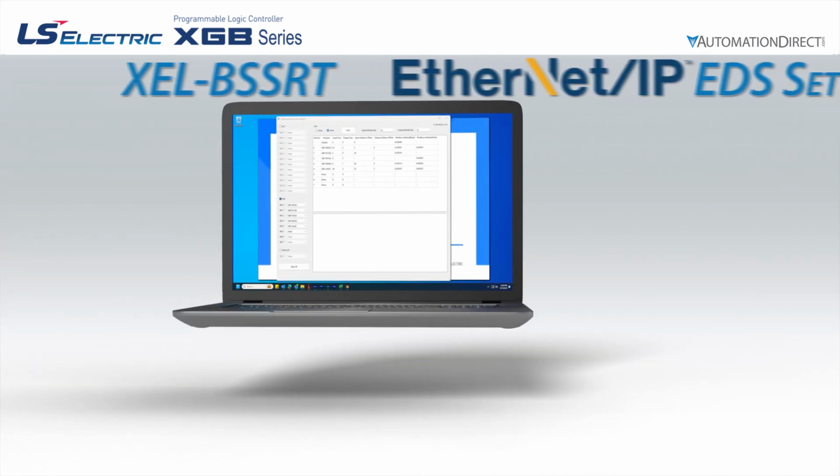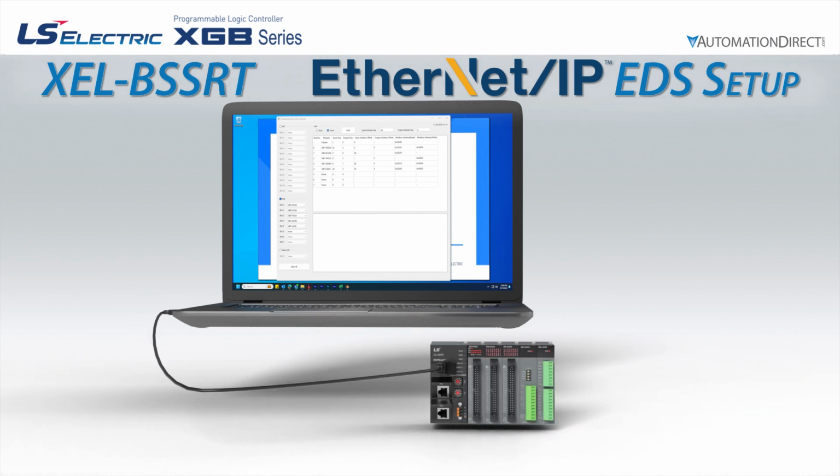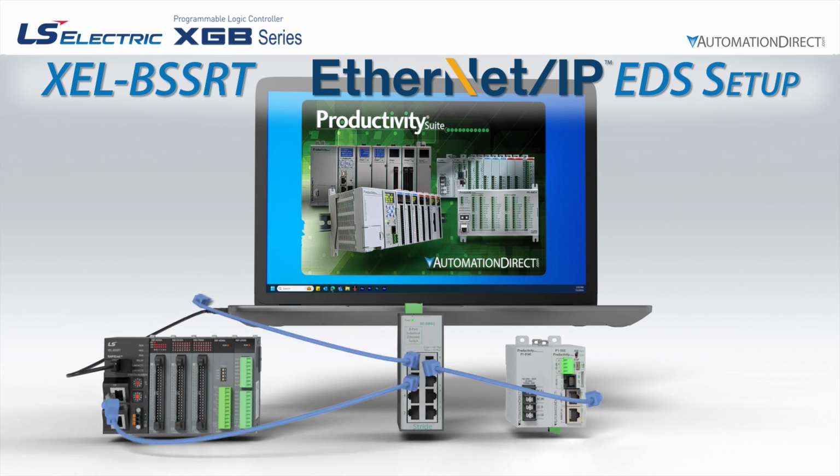Previously, we used the Addressing for Communication Devices software to establish the addressing for our BSSRT input and output information. In this video, we will generate an EDS file using the XG5000 software, and then import that EDS file into the Productivity Suite software. We will also establish the connection between a P1550 and the BSSRT, allowing the Productivity PLC to control the remote I/O using the data offsets.